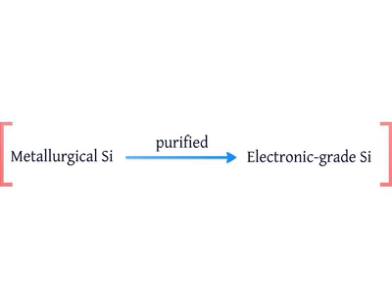Then the metallurgical silicon, of course, is not very pure. It gets purified by typically another chemical process which uses hydrochloric acid, which I won't go into much detail on, but you can read in the book. It forms what's called electronic grade silicon, which is very close to the purity that one wants.